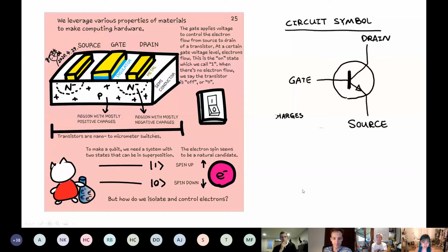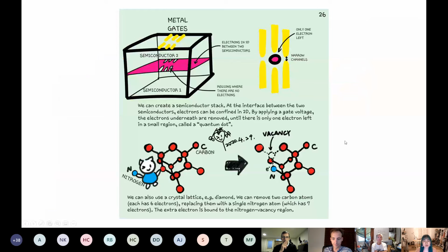So a natural example would be something like an electron spin up and down energy levels. And how do you trap electrons? You can put them in quantum dots, which are fabricated semiconductor sandwiching a thin layer of electrons, and then you can confine your electron into only one dimension, and you can trap electrons there and manipulate its spin up and down. So you can create your quantum bit 0 and 1s.